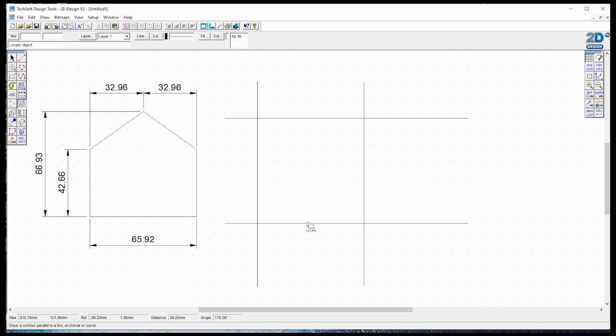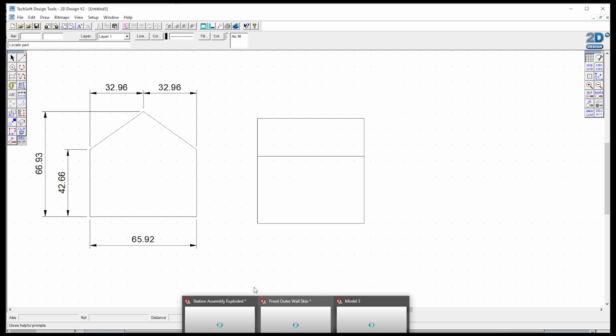And again, I'm going to click that just up from the bottom. So we've got all our basic geometry done. We used the line tool once to draw our initial vertical and our horizontal line in, and we've used this contour tool. What I'm going to do now is select a delete tool. So this is the third tool that we'll be using, and I can trim away the excess lines here that we really don't need, just to clean this up.